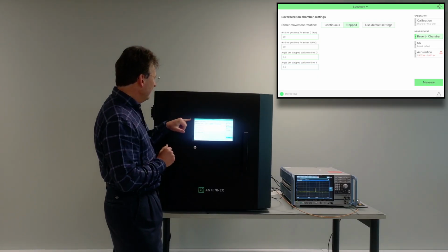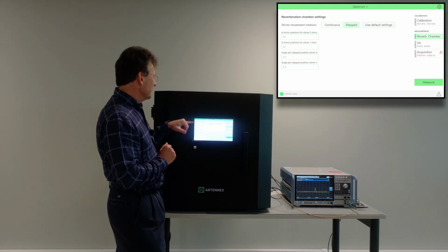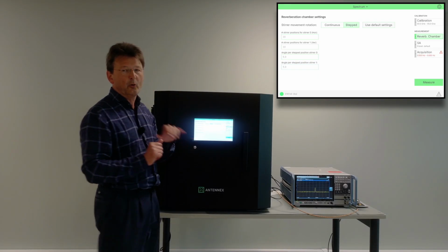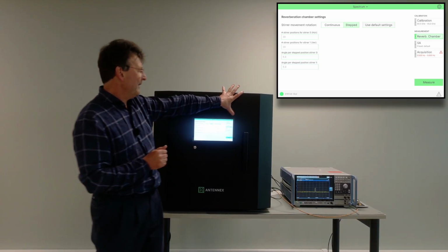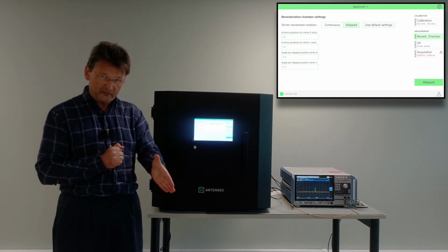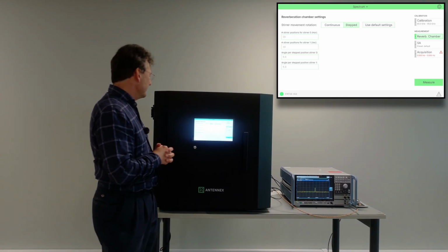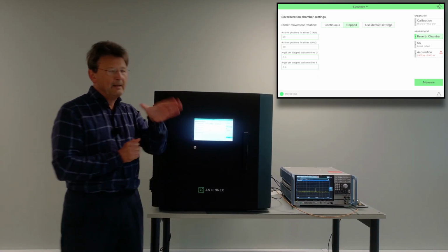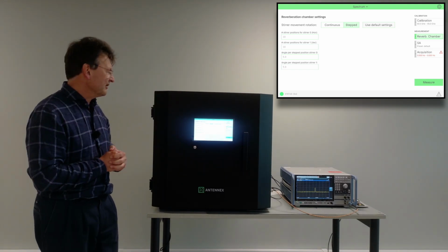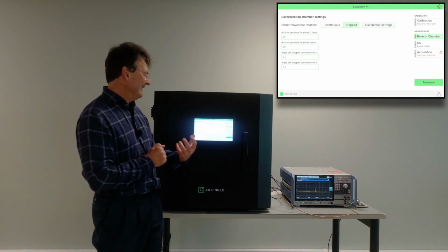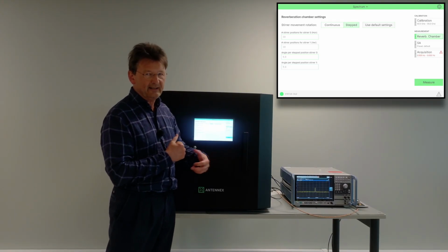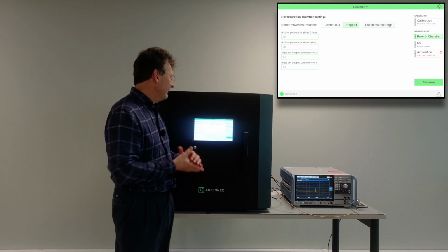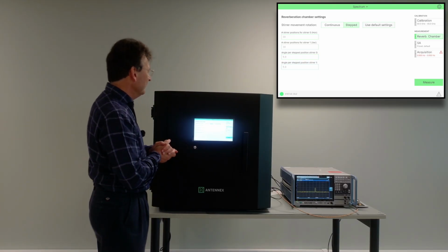And there you can see that for the positions, there are 10 positions for the horizontal stirrer, which is positioned at the top here. And then in the back, there is a vertical stirrer that also has 10 positions. And we are doing, in fact, steps of 5 degrees each time. And then for each setting, the spectrum analyzer is going to measure the power spectrum and then all the data is collected. And there is some averaging applied at that moment.